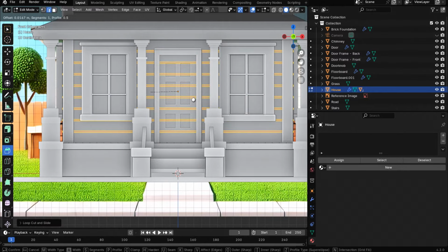Okay, so this is real geometry now. You don't have to. You can just add another array modifier if you want to, but that's just something I did. So I'm going to add another array modifier and then line this up. Use your factors over here to line this up just on top of that first row of tiles. Okay, and once you've got that, and then bump up the count, and you'll create tiles all the way up your roof.